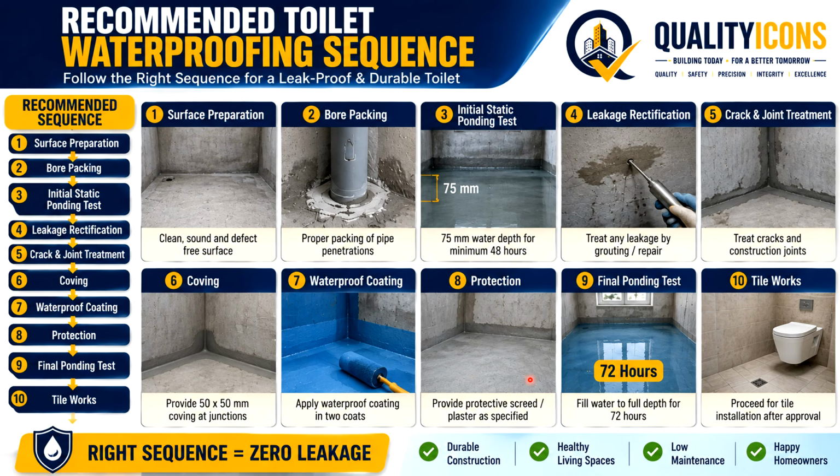Protect the waterproofing system, that means provide protective screed or plaster as specified. Final ponding test, this is also 72 hours. Final static water ponding test.